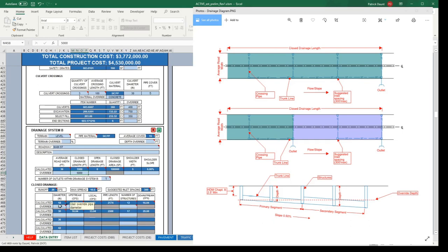So you can see if we started off with 24-inch to maintain the existing 18-inch coming into it, we need 2174 linear feet of pipe, and then 16.04 will dump down to the next highest pipe, which is 30-inch, and then 1304 will be provided to the 30-inch pipe locally, and that will take care of the rest of the area.